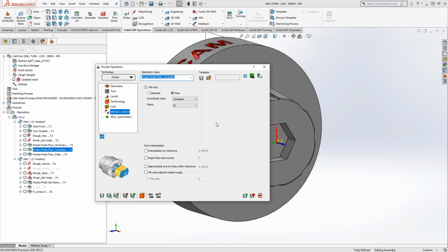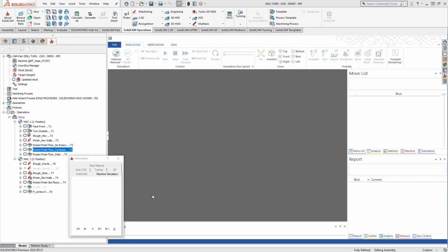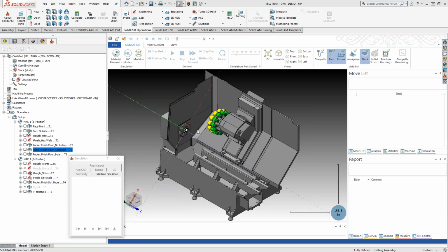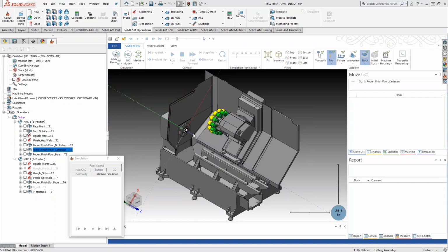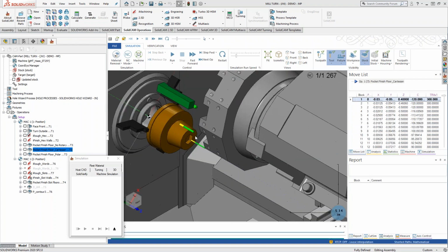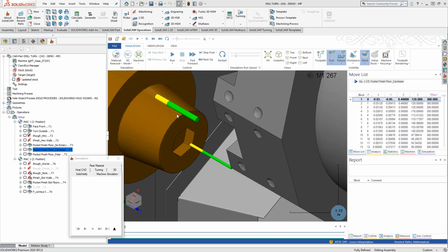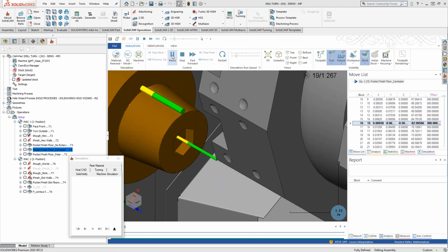So what this is going to do is generate a toolpath that, if we look in the machine sim, and again, I'm going to be going back and forth between the machine sim. So this time I'm going to leave the machine sim open so we don't have to load it every time. But this one is using the fourth axis checkbox set to Cartesian. And once we load this up, this will be the difference between Cartesian without the box checked, because it's default, and the Cartesian with the box checked. The part now moves.